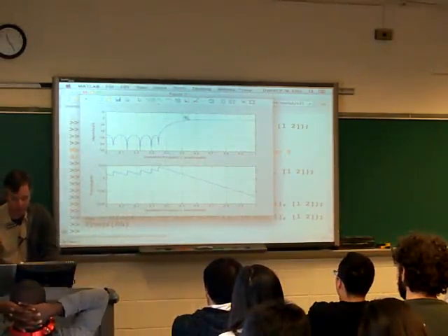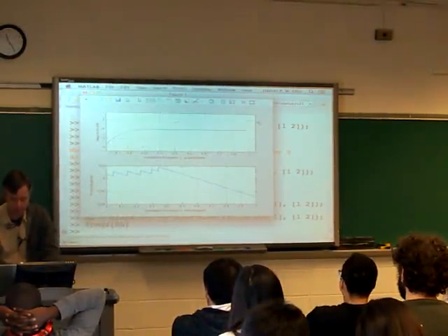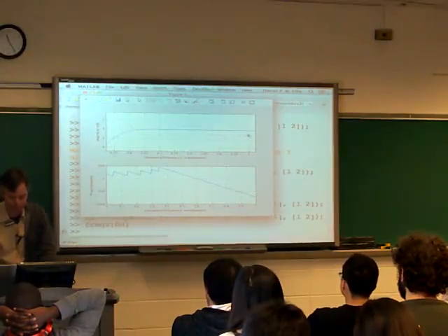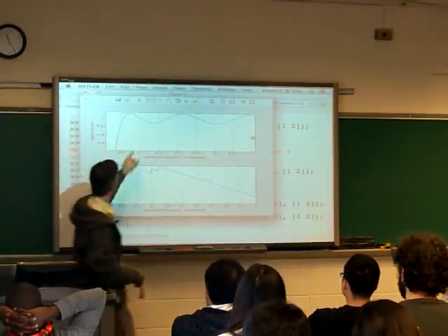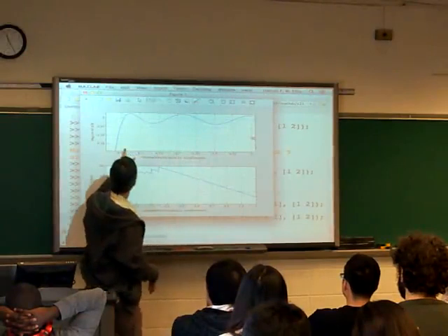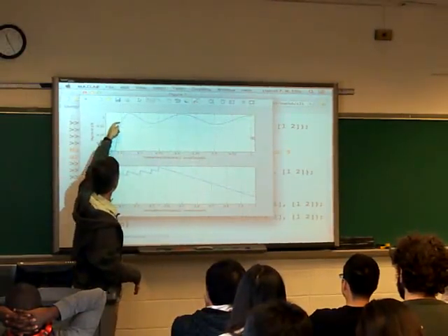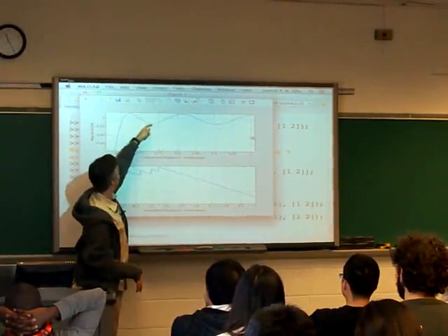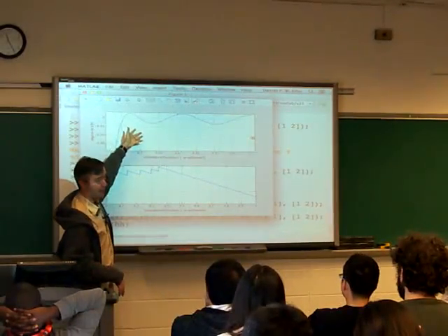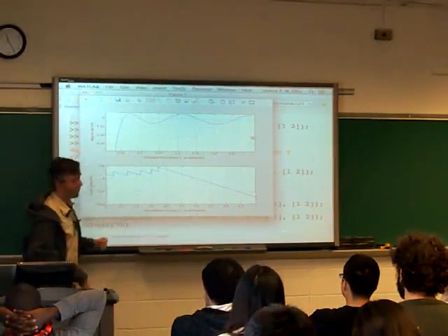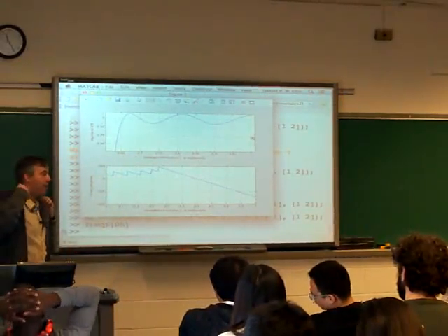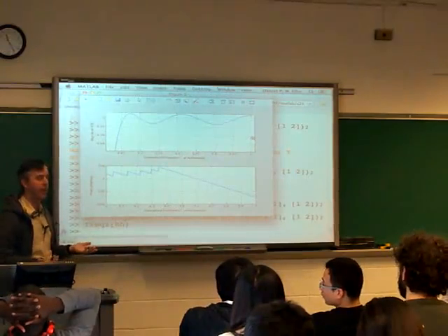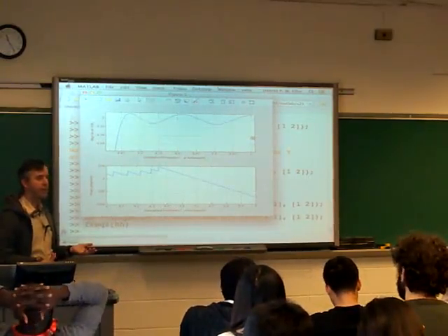If we zoom right in here, you have to zoom right in. Here you can see, okay, these ripples are equal depth. And of course, by design, at 0.65, it's just at the very level of that ripple, because that was the band edge that we asked for. So that's what it does. But it conveniently finds us our filter, but the one thing it doesn't specify is the ripple depth.